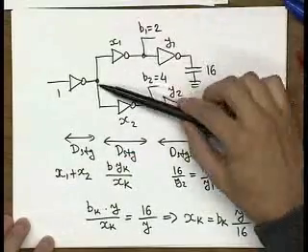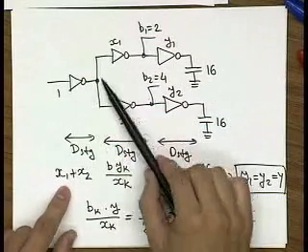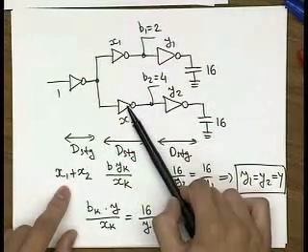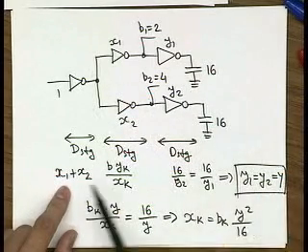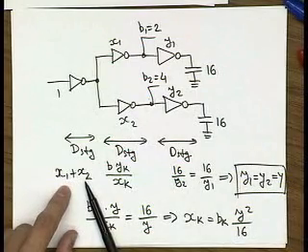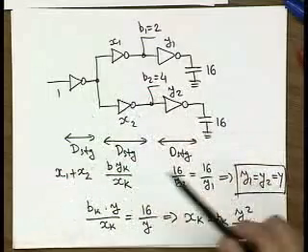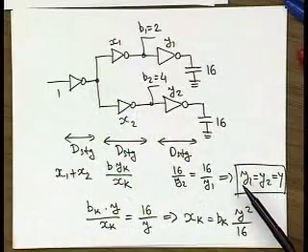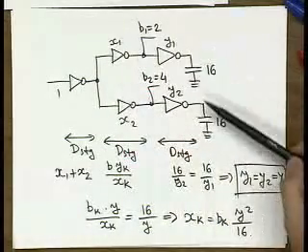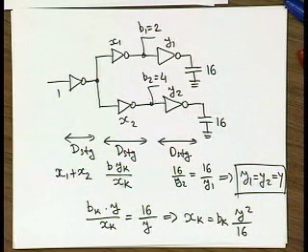You couldn't really do branching over here because this is in a sense branching, since the total fan out is equal to x1 plus x2. Both paths are important now, but you don't really know the ratio of x1 and x2. You have to analyze this entire circuit jointly and then figure out the relationships in play that will provide equal delay in both stages and that is also minimal. Does this answer your question? All right.